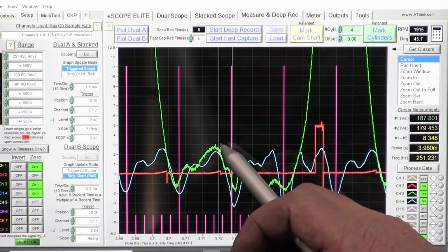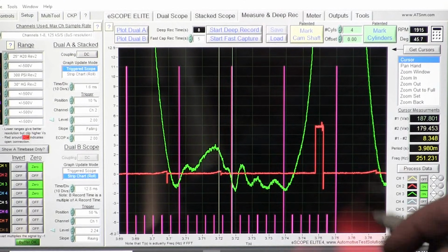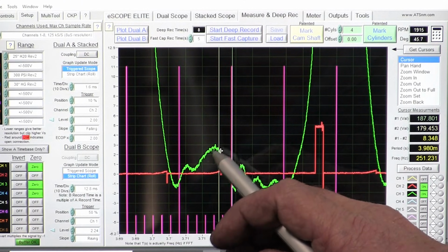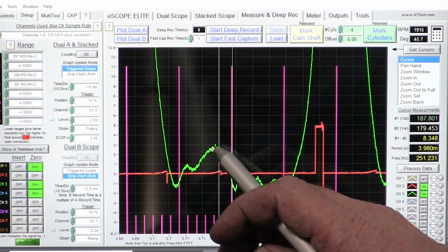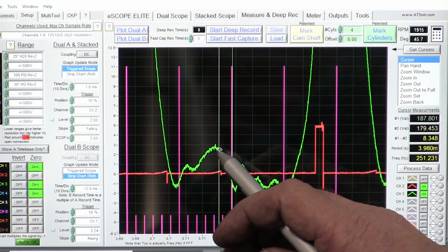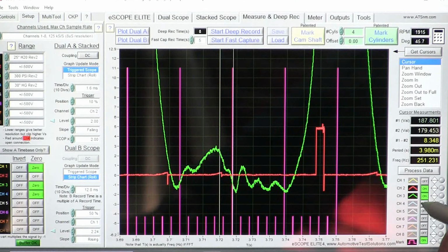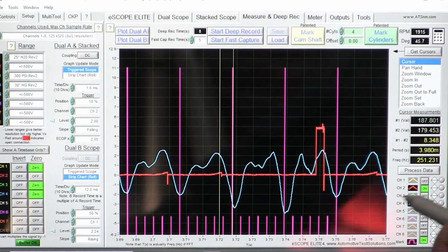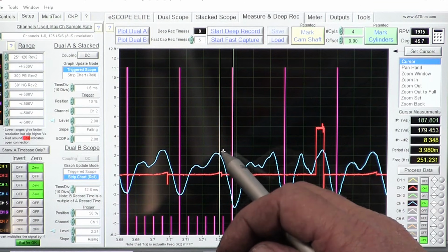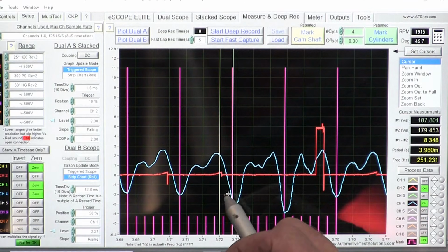Now I can see that let's shut this off, I can see that that had a pull. I'm pulling vacuum, and then all of a sudden the valve opened and this goes down. Now if I look at the intake and I compare it with this, do you see how the intake came up and it's forced down also?